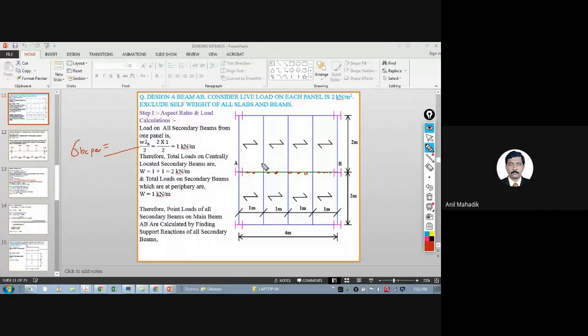As there is full restraint, definitely I will take this value as 0.66 Fy, which is 165. That's it. Even though these beams are connected here, the full restraint is there due to the slab by using these shear connectors. So as it is fully restrained, I can take full stress.